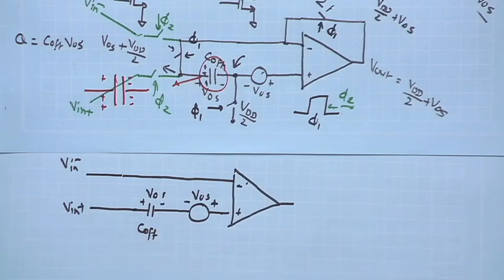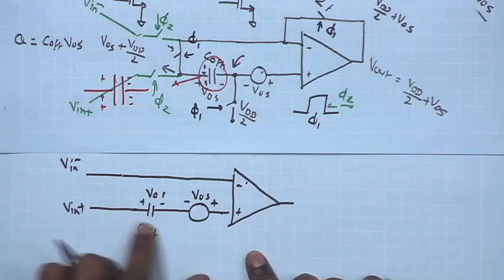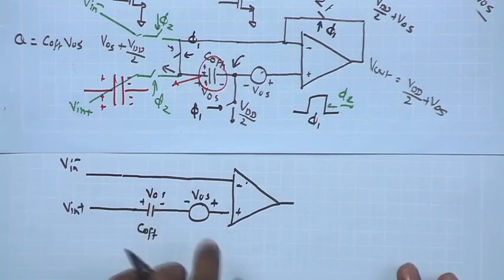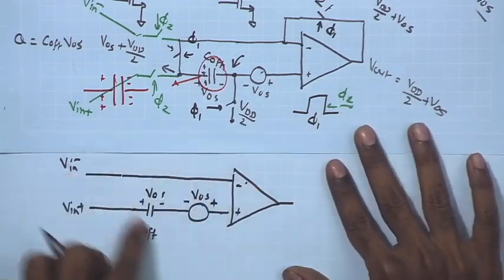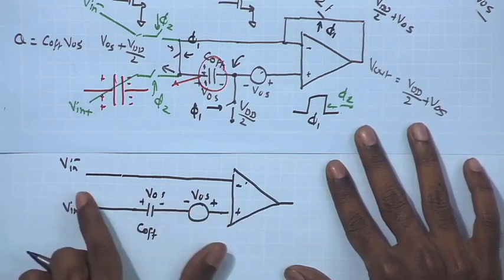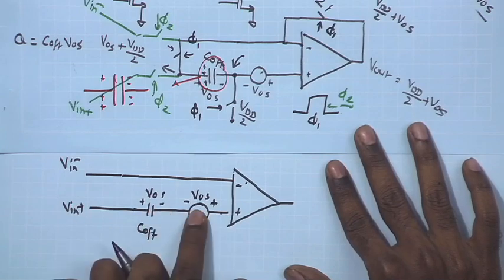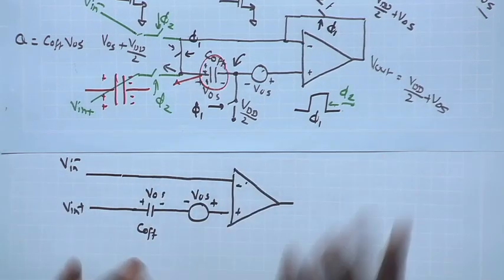The internal terminals. Therefore, what I can say is that the stored voltage across this capacitor has been able to cancel out or mitigate the effect of mismatch. So, whatever offset was present in the amplifier, it captured it across its terminals, and that came in series with the amplifier's offset, and therefore it nullified the effect, and then I have close to an ideal amplifier with 0 offset.